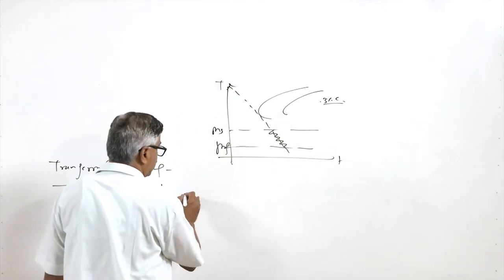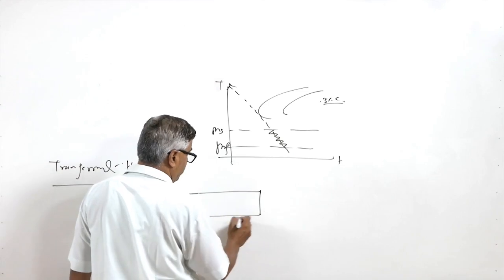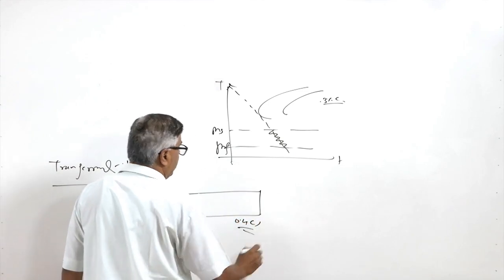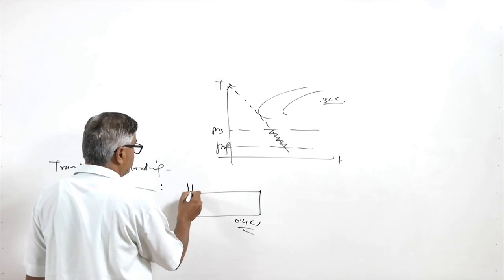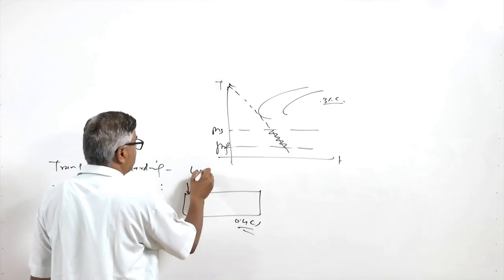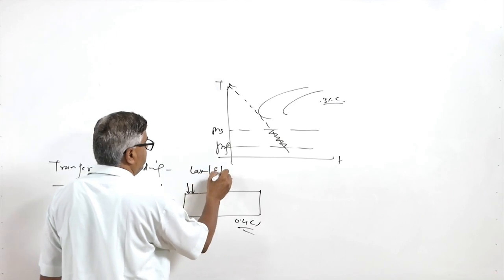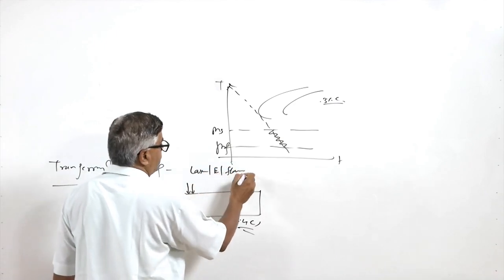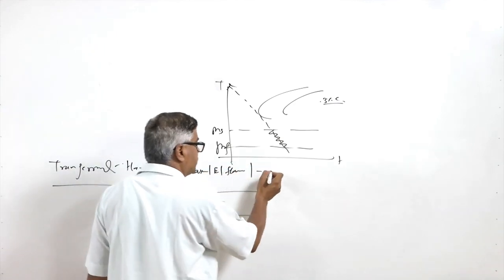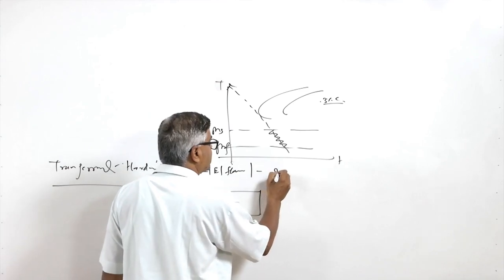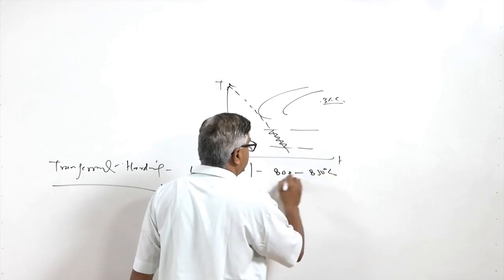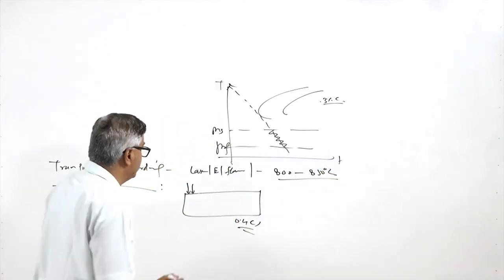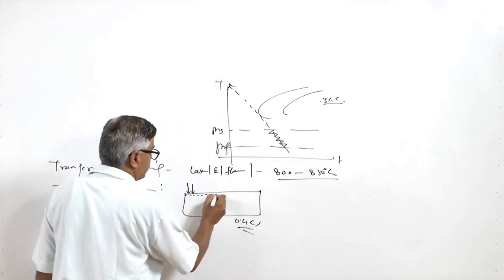The component having, say, 0.4% carbon steel has its surface heated through a suitable source of heat like laser, electron beam or flame, in such a way that it gets heated above 800 to 850 degrees centigrade. So homogeneous austenite near the surface layers is formed.